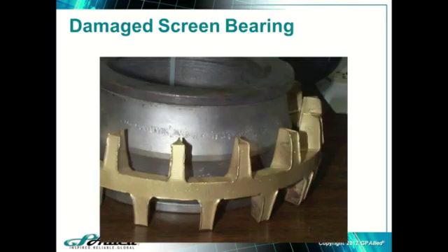Right? So we got to ask ourselves, well, here's some examples for those of you who've never seen spalling. I wouldn't say it's a mild case, but it's not severe. It's severe from a vibration standpoint, an asset health standpoint, a maintenance standpoint. But you know, we've all seen bearings with much more severe case of spalling than this. But that's what spalling looks like.